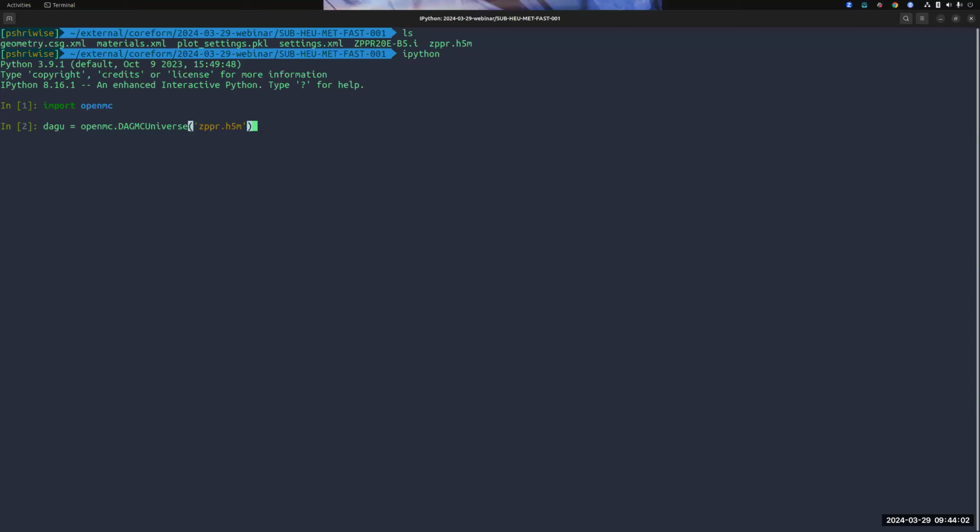And I just wanted to note that the boundary conditions that we've applied within this model are going to be respected in the same way that CSG boundary conditions are used within OpenMC. So the fact that we've set vacuum boundary conditions within this model, if particles reach those before reaching an exterior CSG surface, for example, that has its own set of boundary conditions, then the ones that the particles see first are going to be used and respected.